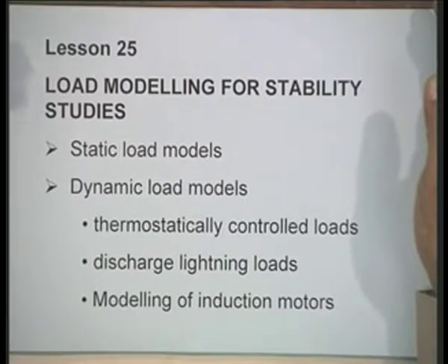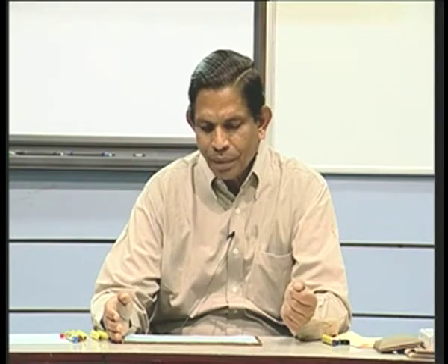The dynamic load models are essentially required for long term stability study, voltage stability, and when you want to study the interior oscillations, right. Now, today we will briefly discuss how the loads are represented as static loads and dynamic loads.